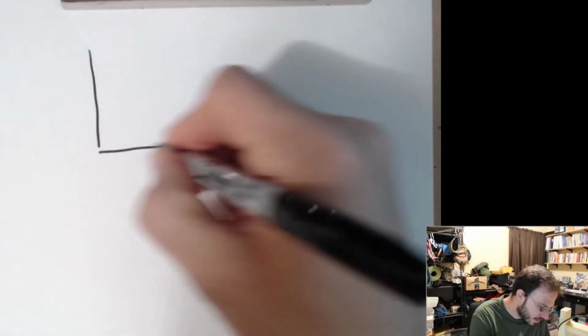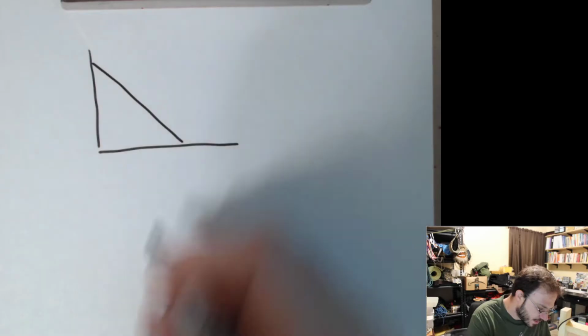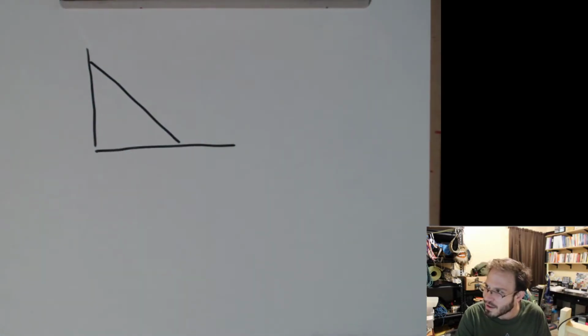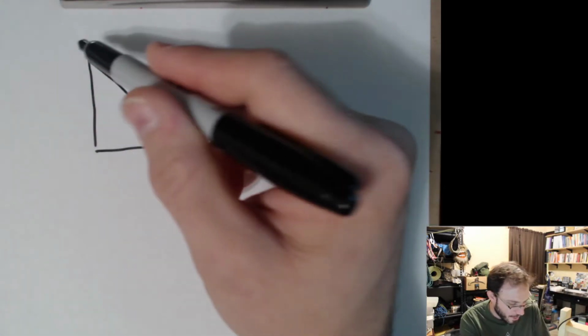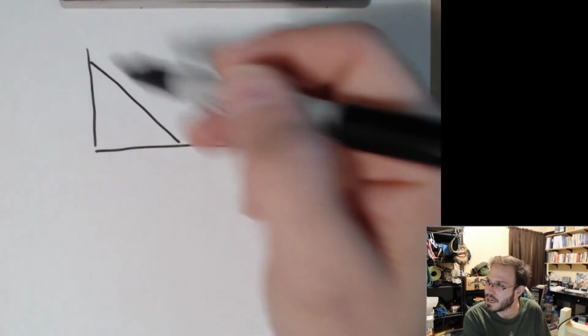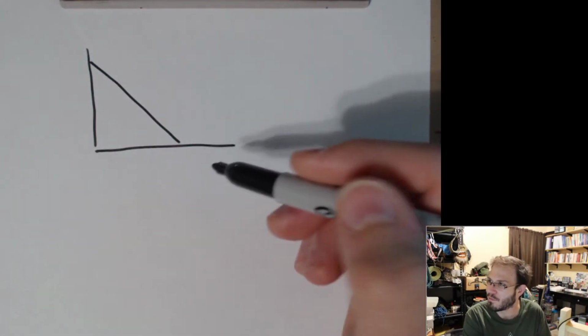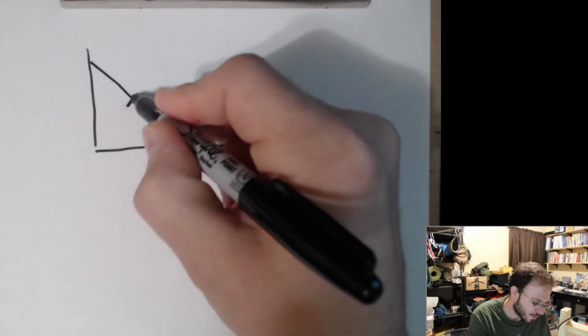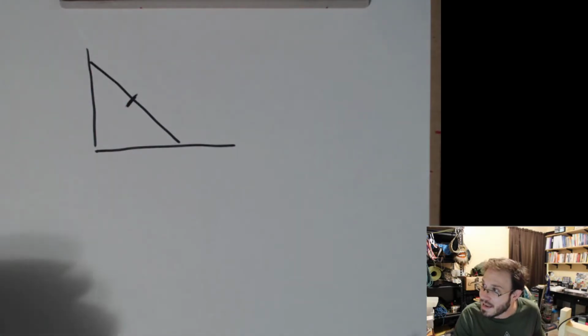Okay, so optimum Q point. Hopefully, if I tell you I don't want to be too much towards saturation, I don't want to be too much towards cutoff, where's my optimal point? Yeah, it's right here, right? It's in the middle.